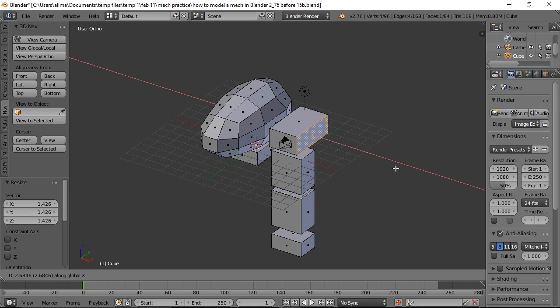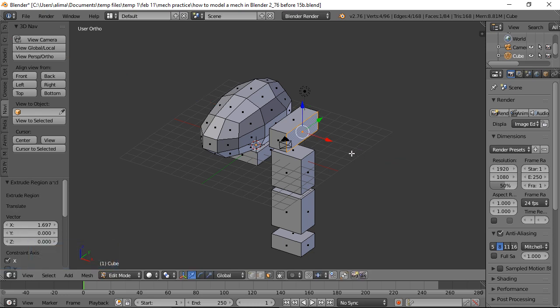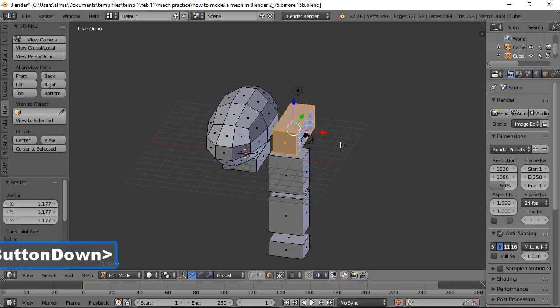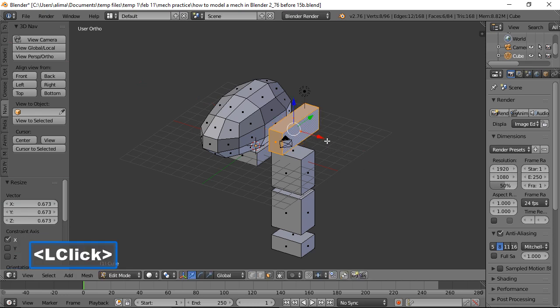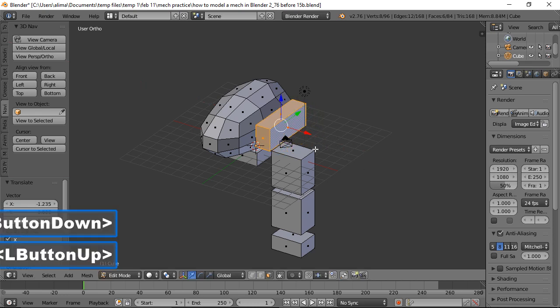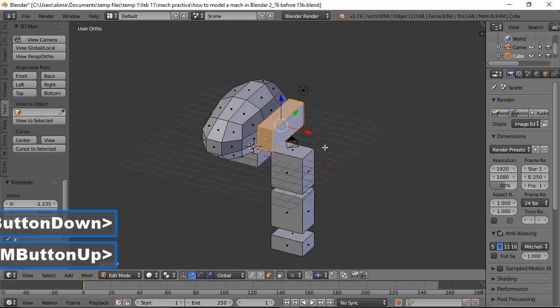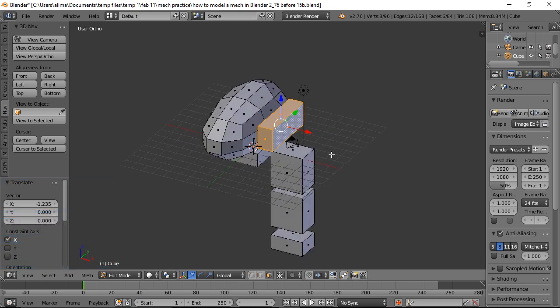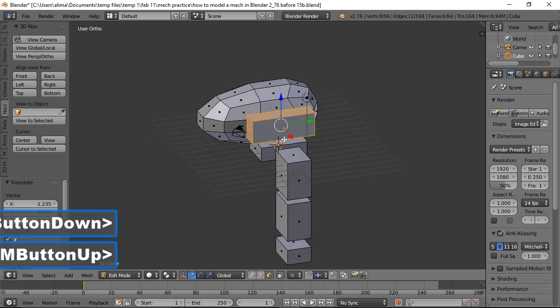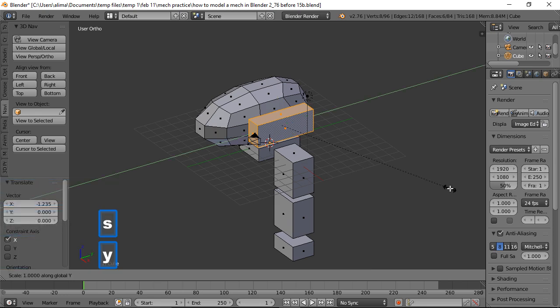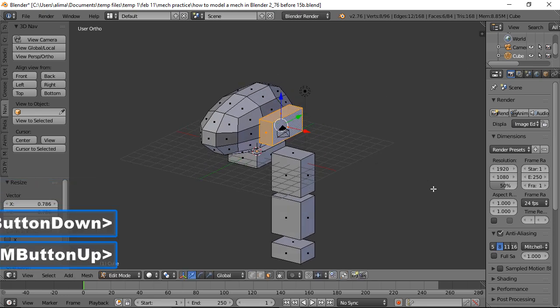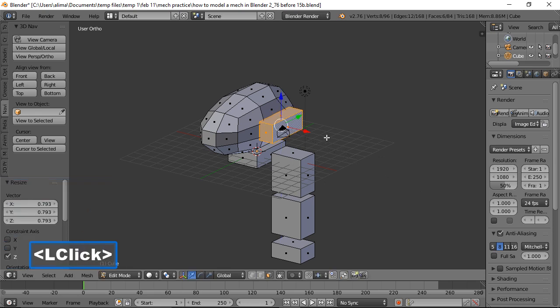Then I want to push it a little bit. Left click to lock this in. I'm now going to hover here, press L, press S to scale this up a little bit bigger. I'm going to press S to scale in the X-axis. I'm just going to make this a little bit thinner. And basically this is going to be a part that our weapon attachments come out of. So actually, let me press S to scale on the Y-axis, then S to scale on the Z-axis.